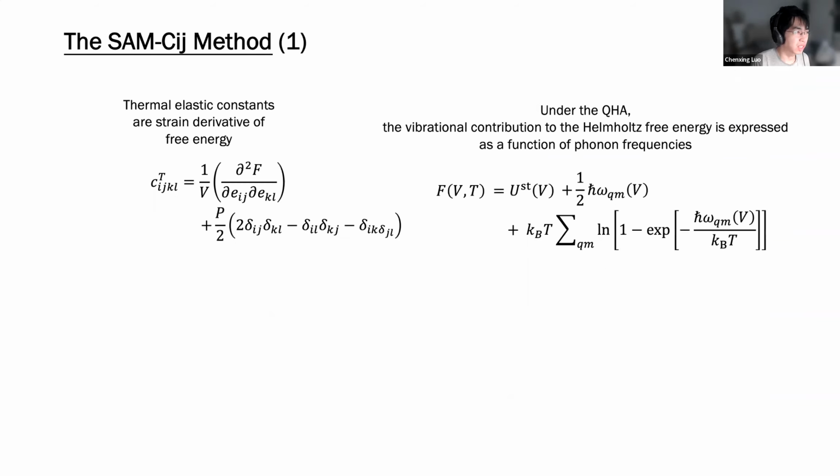And for the semi-analytical method, we will be based on the quasi-harmonic method, where it is defined in terms of the free energy. Here on the left, I'm showing the elastic coefficients defined as a second-order strain derivative of the free energy.